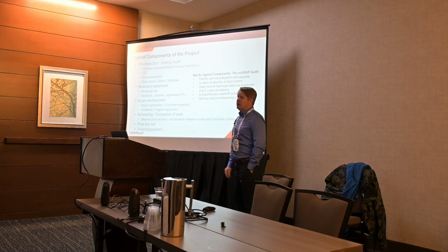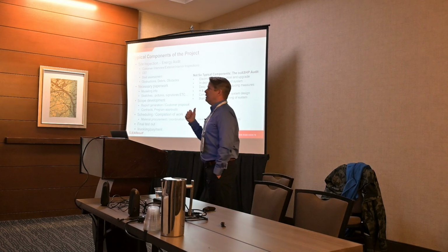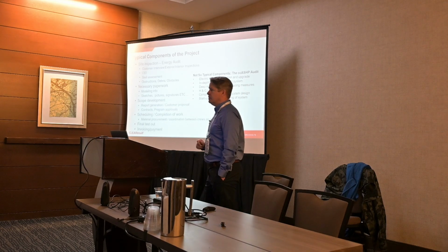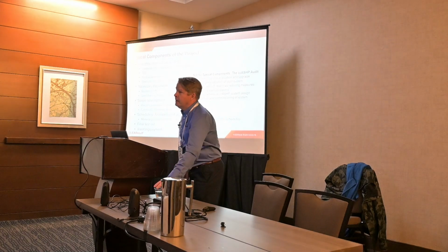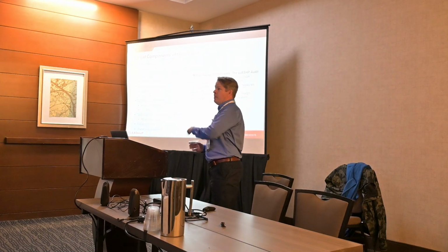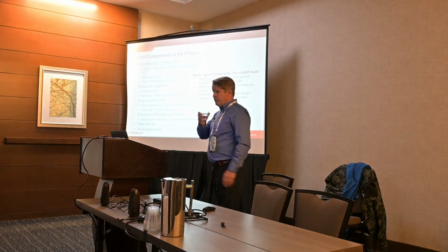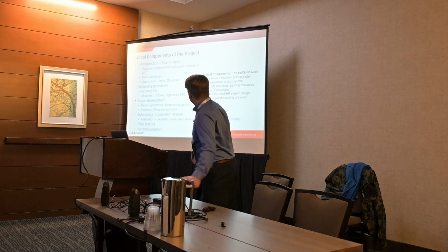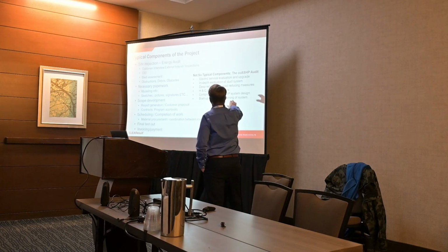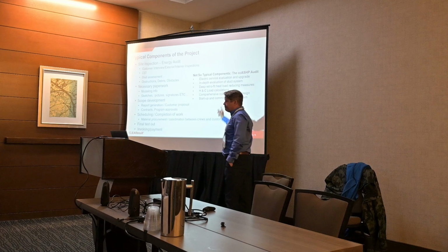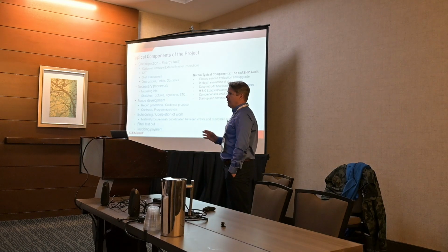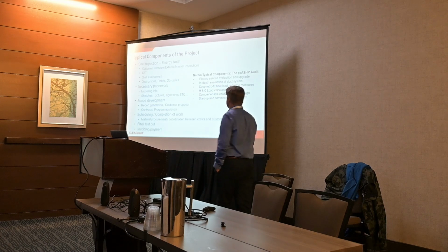Heating and cooling load calculations, okay? Is the necessity to do heating and cooling load calculations unique to cold climate air source heat pumps? No, it's not, right? This isn't new. Nothing I've said here is really new, right? Every system, before it's installed, should have an accurate heating and cooling load calculation. This right here is why we need to gather more data on the house. We need to know about the windows, the direction, the type they are, the shading. All that sort of information has to come off of your site visit.